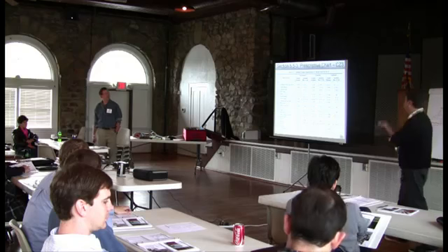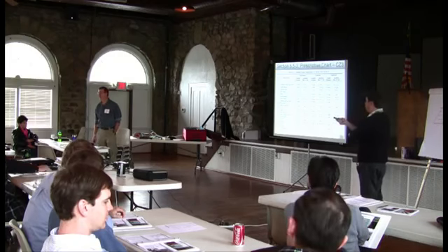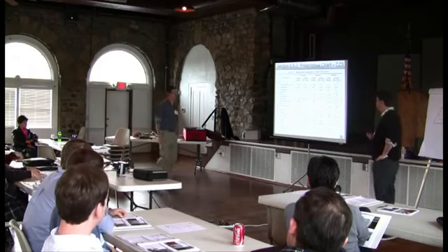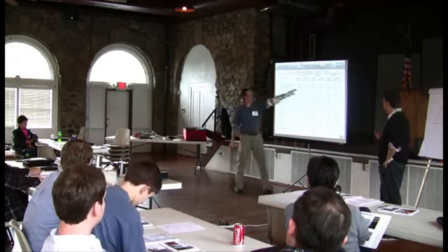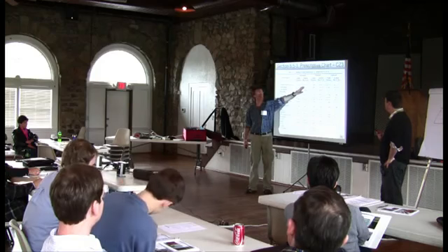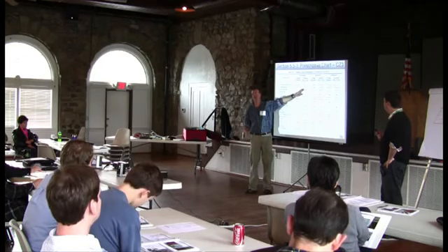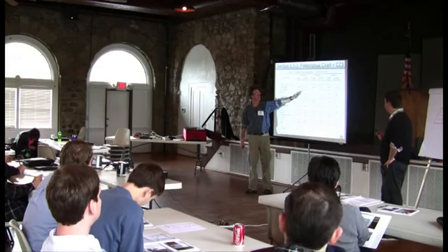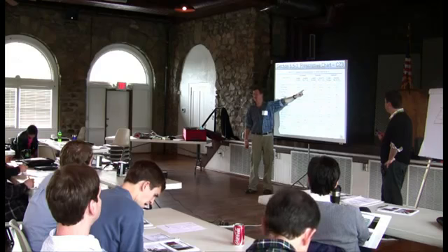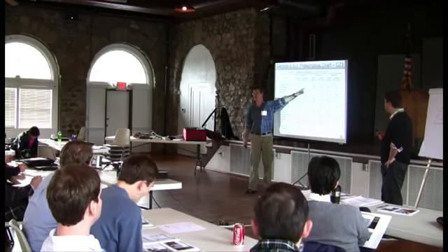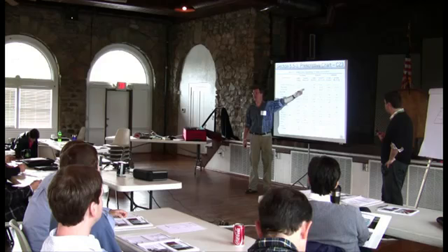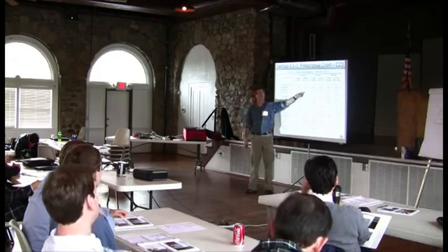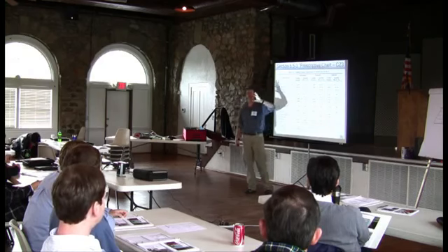Moving on then, after roofs, we've got walls. Wait a minute, hold on a second. I want to make sure that we really remember these values. The big number we want you to take away here, like I said, there are two big changes on this chart from the last version of the code. That's no longer R15, that's R20, and later on we'll talk about the steel studs. But metal buildings, it's R19, and you can see that's the least amount of insulation of any of these. So if you think you were pushing too hard, look at the other assemblies. R38 in a flat attic, that's a lot.